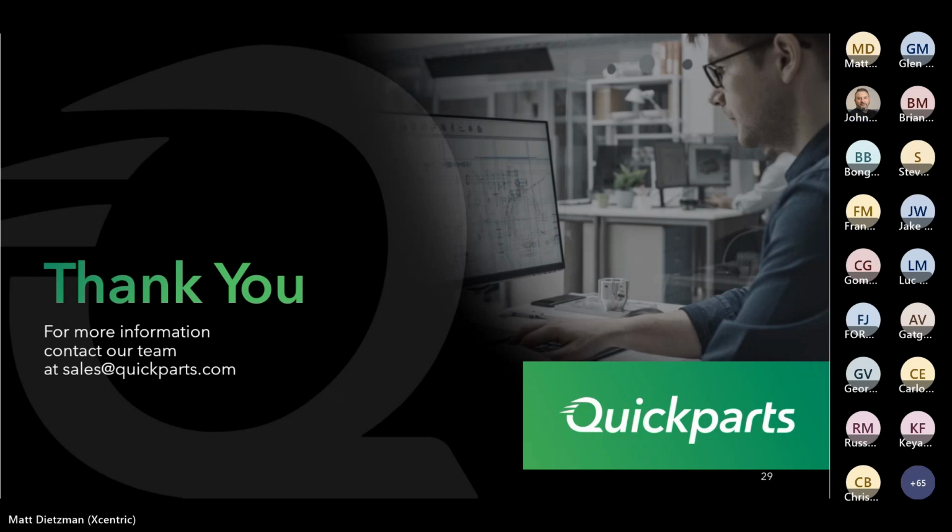If it's a visible parting line, we've had some instances where customers had parts where the parting line had to be in a certain area just due to the design and to make it moldable. The last resort is post-processing, where it's either sanded off or removed. And typically in those cases, the parts are painted or coated to cover that. But I don't know, Glenn, Brian, if you have any other thoughts.